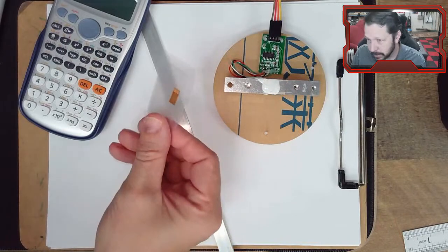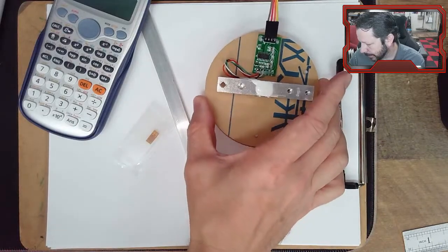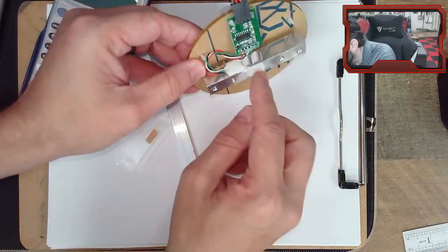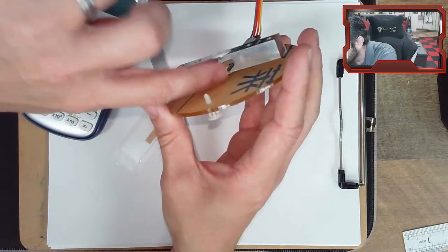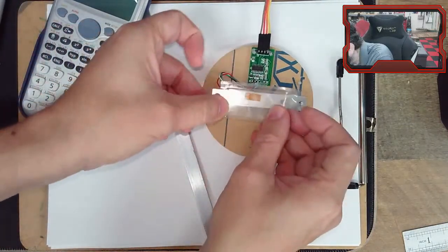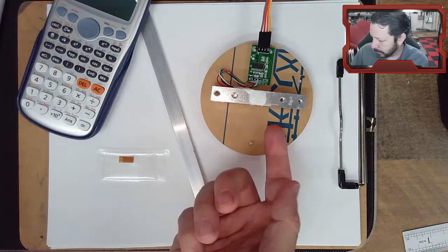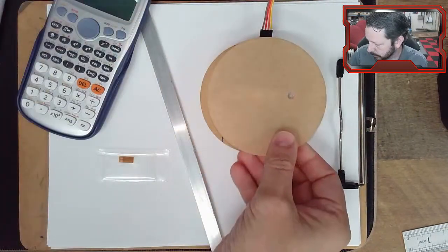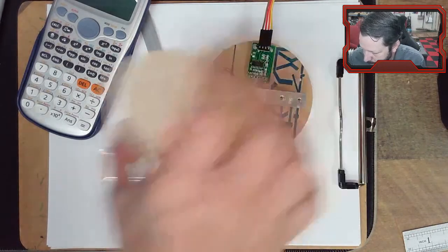Here's a strain gauge in this little package. This is kind of like a load cell. It's a little force sensor underneath this, and I don't know if you can see on the bottom, but there's one on the bottom too. There's a similar, but I guess smaller, or maybe it's the same size, strain gauge underneath there and under the bottom here, and this is a little scale, so we can use it to figure out the weight of something once it's calibrated.